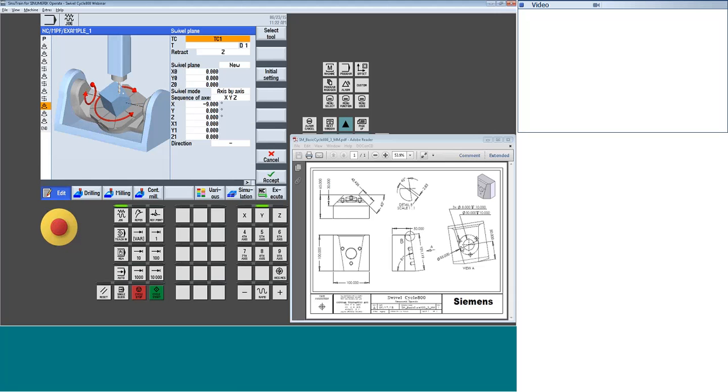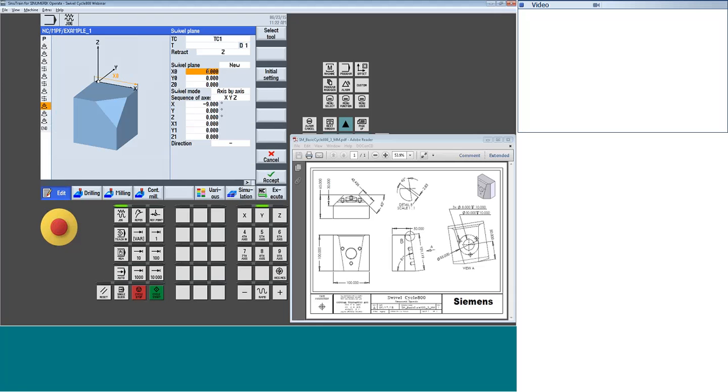This is a case where I would stage my 0 over, apply a rotation, and then stage my 0 down, because I know relative to the surface, the center of that pocket's 50 mil down this plane. It's down there. So I couldn't do the 50 mil up top because that would have been in space and then rotated, and then my 0 location would have been off. So again, all this stuff depends on how it's dimensioned.